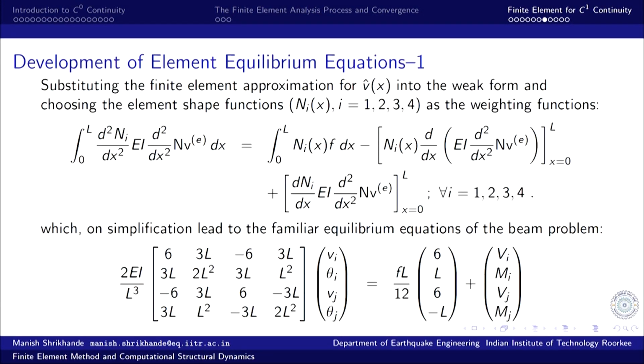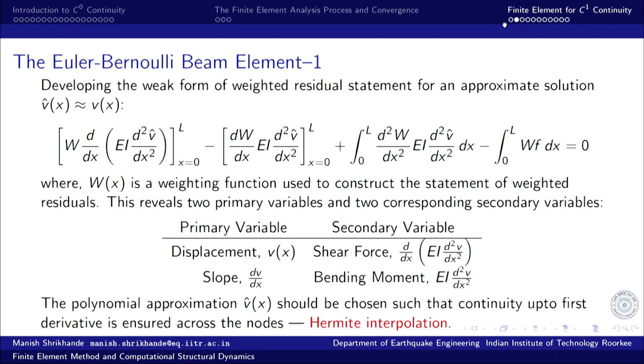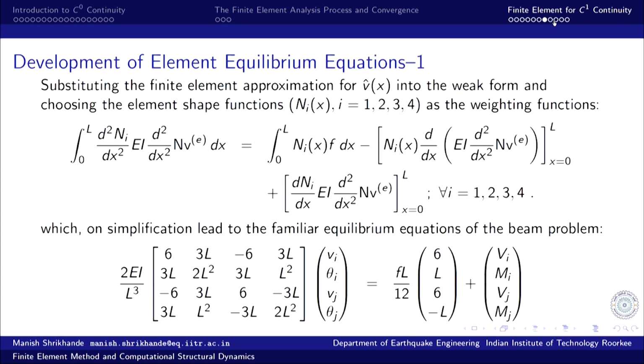So, with this development, the finite element model is of course defined. We already have our weighting function and the weak form of the weighted residual available with us. All that we do is replace W with the respective interpolation functions N1, N2, N3, N4, 4 weighting functions, one after the other.